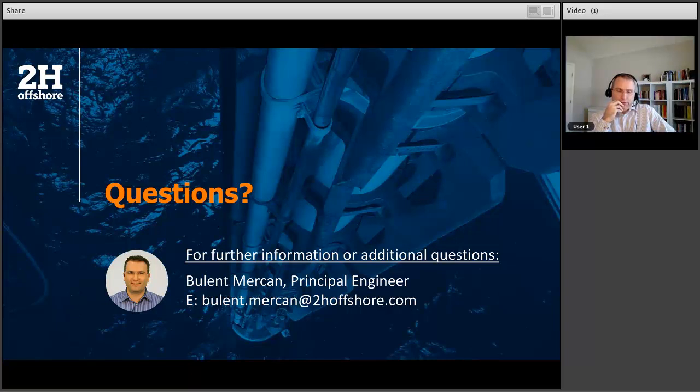Next question: how do you deal with mean stress issues for fatigue life prediction when the tensile stresses are varying along the course because of weight and wave motion? Very good question. Most of the time it can be included in the SN curves, so you can define your SN curve such that it also includes the mean stresses.